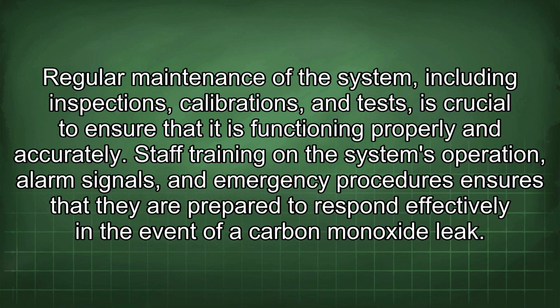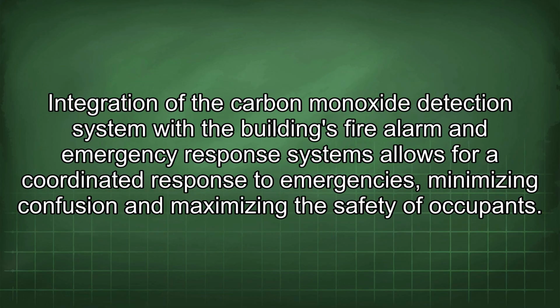Staff training on the system's operation, alarm signals, and emergency procedures ensures that they are prepared to respond effectively in the event of a carbon monoxide leak. Integration of the carbon monoxide detection system with the building's fire alarm and emergency response systems allows for a coordinated response to emergencies, minimizing confusion and maximizing the safety of occupants.